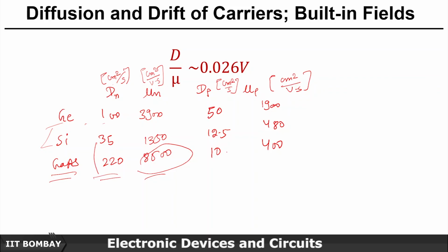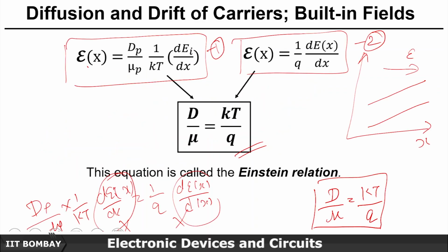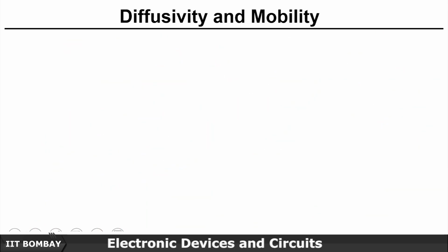Now, we will talk about how this band formation takes place, but let me just discuss the relation of this diffusion coefficient with the temperature. So, if you remember when we talked about the mobility in the last lecture, it was very evident, we discussed in very much detail how it depends on the temperature. There were two major scattering mechanisms that we discussed, because of the impurity and because of the lattice atoms, and it varies something like T to the power, for mu, if you remember in the last lecture.